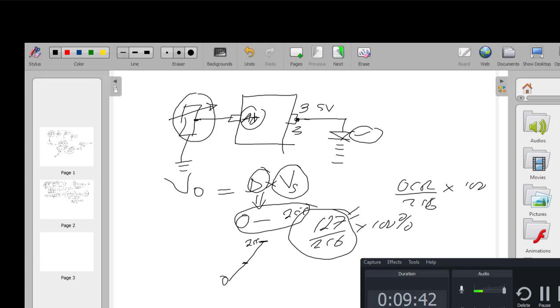We're going to use those digital values as the duty cycle that we can get, such that we make the system dynamic and interactive, so that I can determine what duty cycle I'm sending to pin number 3 depending on the value that is actually read from A0.